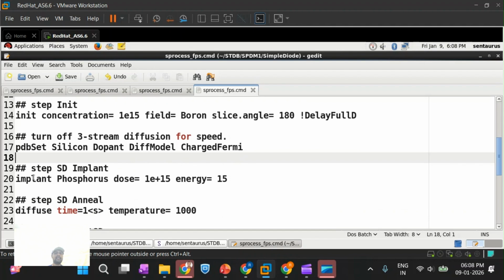Now doping can be done in two ways. One is gas phase diffusion or solid phase diffusion. The other is implantation. Implantation is unit 2, but anyway, let us use this command. Don't worry, we will discuss them in detail in the theory classes. So implant is just one way of doping. Now we took the wafer, we started doping them. In implant, we strike the dopants into the wafer. Not deep, near the surface of the wafer. So we strike them.